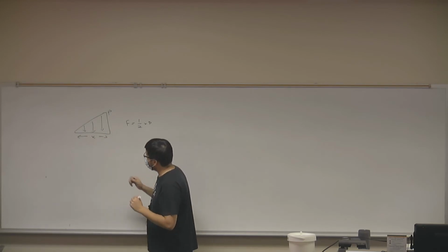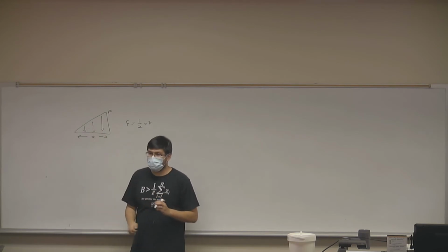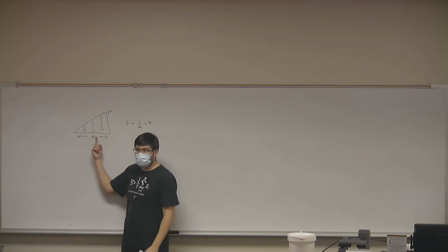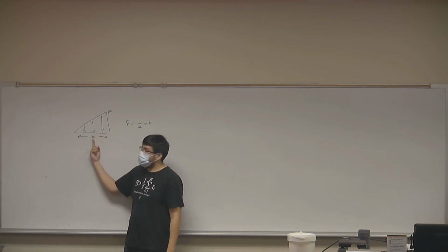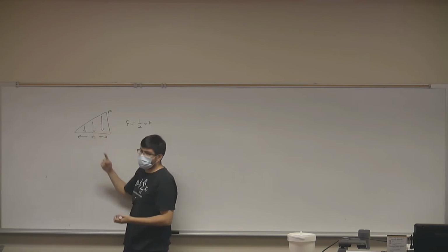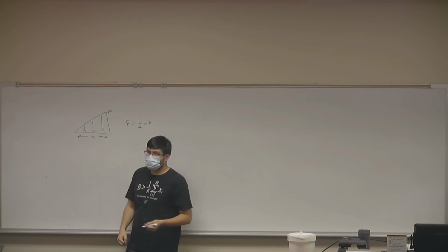And this centroid is the geometric center of your shape. Think of it this way: if you were to balance this triangle on your finger, would you balance it on the center? No, because you'll have more weight on one side. So where is that balance point? At 2/3. Okay, so that's just for triangles, though, right?